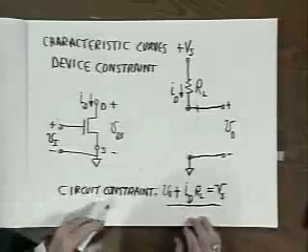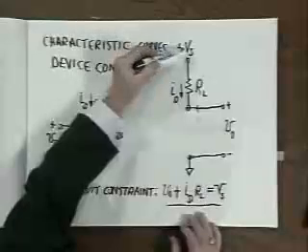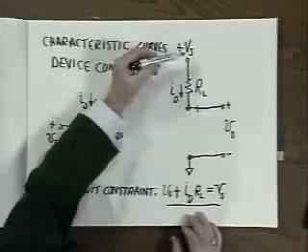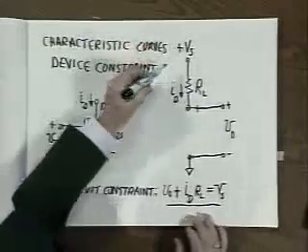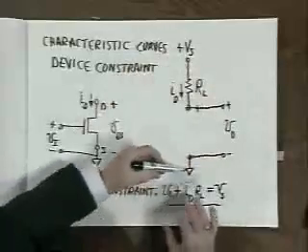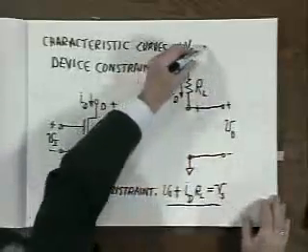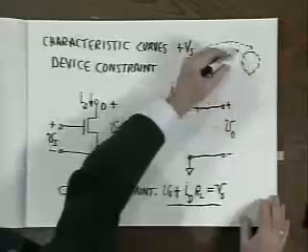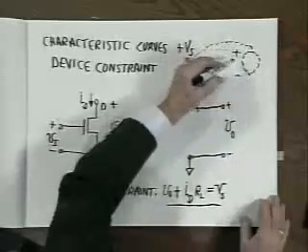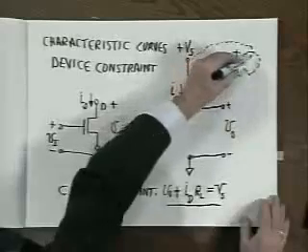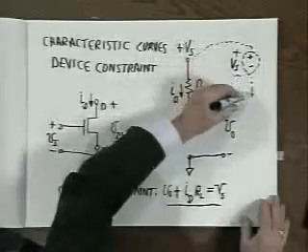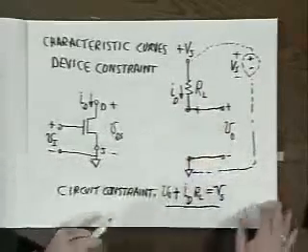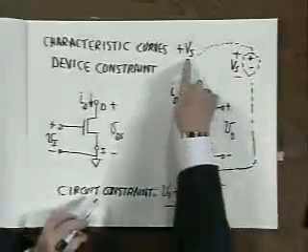I should have said earlier, and let me make it clear now, that when I show a source voltage like this sort of hanging out by itself, there is always the implication that the circuit is closed back around to ground. In other words, somewhere out here in a manner that we don't care about, there's a voltage source, plus to minus V sub S, which is connected back down around to ground. The circuit is completed through the source, which provides this fixed voltage.